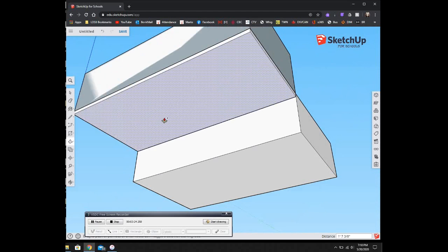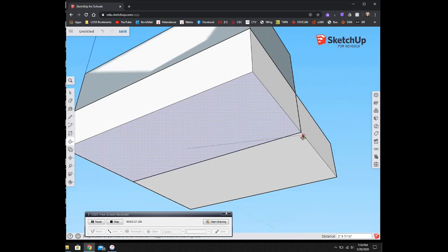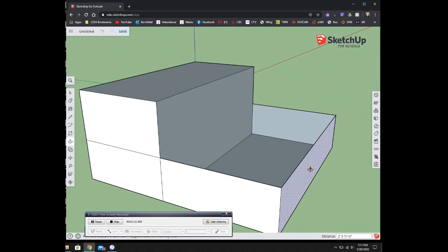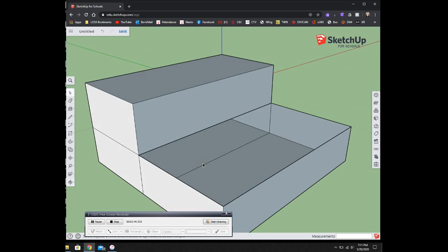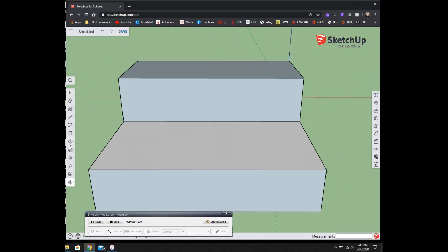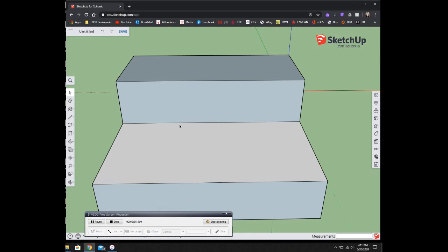There's not a solid object. Essentially, things are hollow, but you can force it to make solid objects. If you have the push-pull tool selected, press Shift. You'll see a little plus there by my icon, and you will create a solid object. You won't have that kind of indented or depressed surface. So you can see all those are polygons. I can click on them, press delete just to see the interior. Control Z is undo, and that put that polygon back.